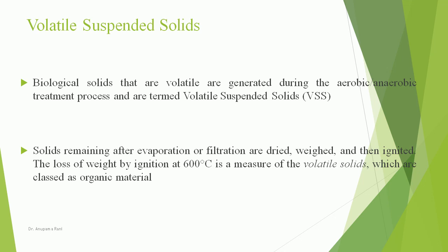Biological solids that are volatile are generated during the aerobic or anaerobic treatment process and are termed volatile suspended solids. The VSS solids remaining after evaporation or filtration are dried, weighed, and then ignited. The loss of weight by ignition at 600 degrees C is a measure of the volatile solids, which are classed as organic material.